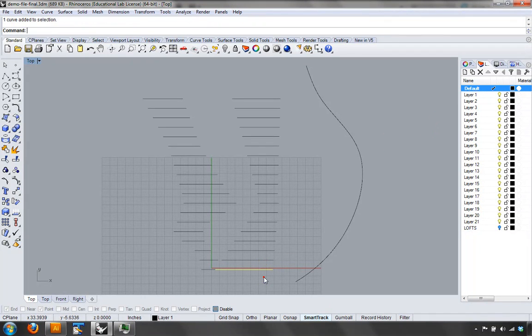And you can take your sections and drag them so that they are centered on this line. I'm holding Shift when I'm dragging so I can restrict them. And you basically take them out of plane, so they're not just straight lined up, but they actually move a bit more in space. A lot of what's going to happen is dependent upon the curve you draw, the curves you started with. But you keep these from being quite so straight, and you can experiment with manipulating them and taking them out of plane.